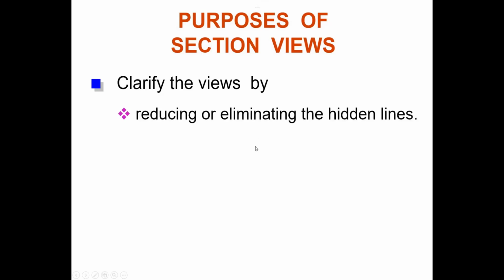As I mentioned just now during my briefing today, the purpose of a section view is to clarify the view of your part, clarifying the view by reducing or eliminating hidden lines. Take a certain component, maybe a casing, bottom casing, top casing, with other features like an opening lid; it depends on your product.